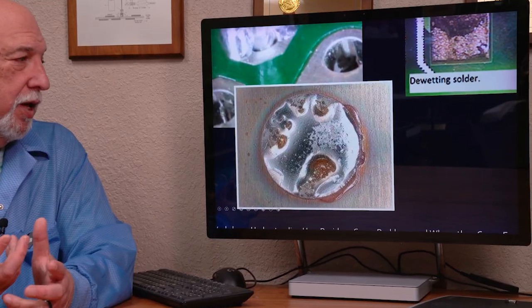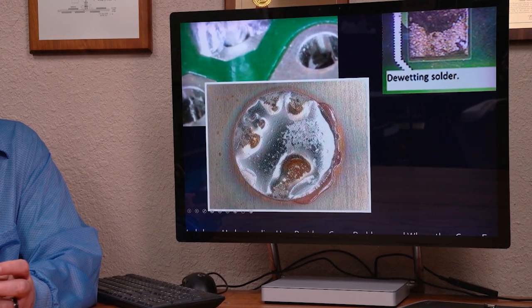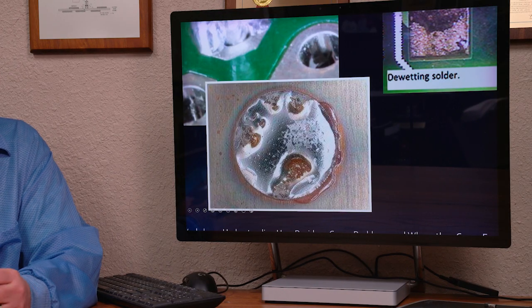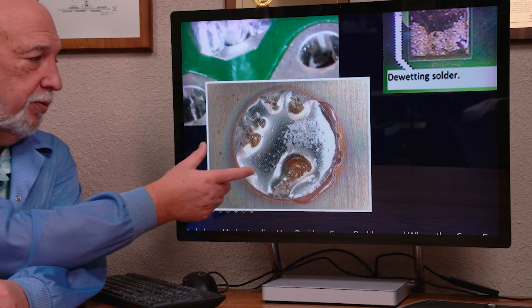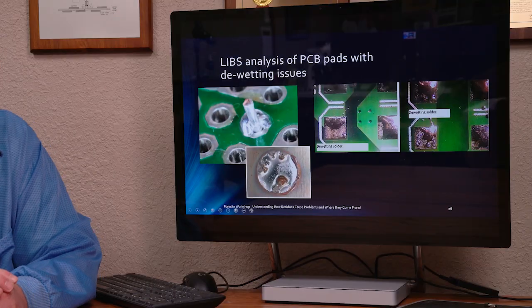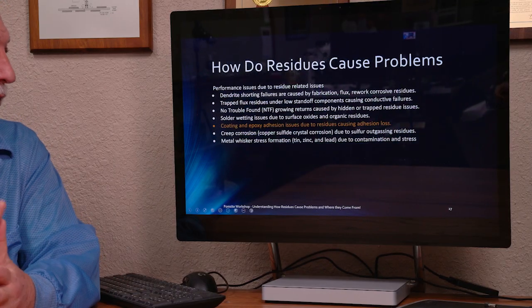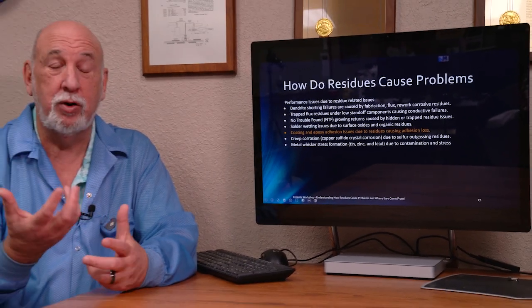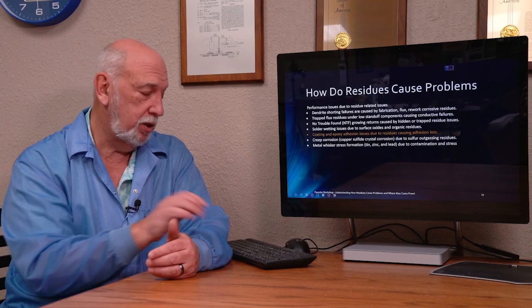Looking at some of the other solderable variables that we see, they become a deposit effect, where there's just so much material that the surface has oxidized during either the first reflow or the second reflow or the selective wave solder process. So all of those become variables that impact those performance conditions. So solder de-wetting does cause problems. It's not something that's an intermittent performance issue unless there's a poor solder connection.